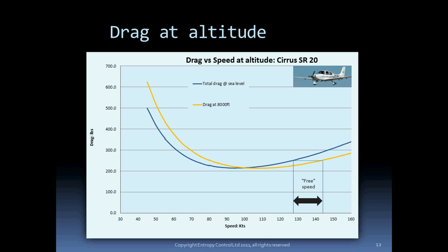At 8,000 feet, your airspeed indicator may read 128 knots, but the true airspeed increases to 144 knots. Again, because the drag is the same at 144 knots at 8,000 feet as at sea level at 128 knots, the air miles per gallon is exactly the same in these conditions. So you get a boost in speed from 128 knots to 144 knots for nothing except the energy and time required to climb to 8,000 foot. And much of that climb energy can be recovered on the descent.